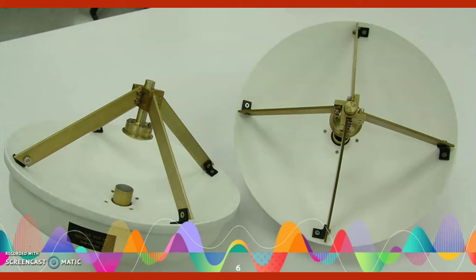So this is an example of Cassegrain reflector antenna. The 223 series antennas feature metallized fiberglass reflectors and are available from 5 to 220 GHz. They offer very high performance in a lightweight antenna structure. These antennas are available in effective diameters of 10 to 84 inches. Because of the low surface tolerance, they provide excellent high-frequency radiation characteristics.